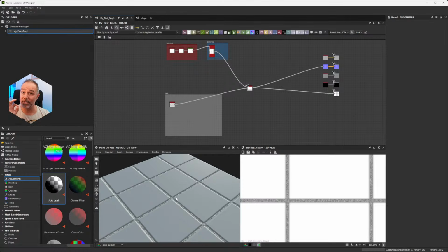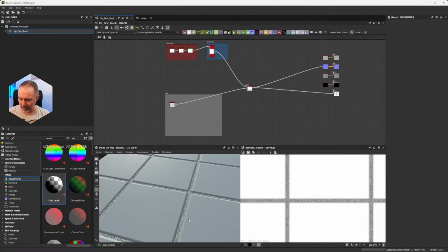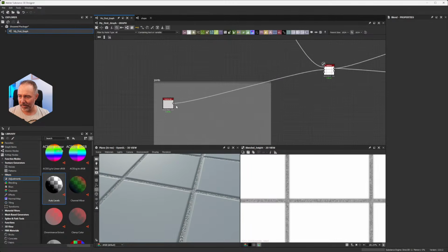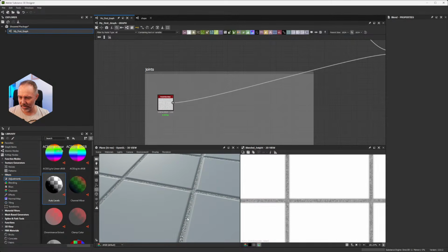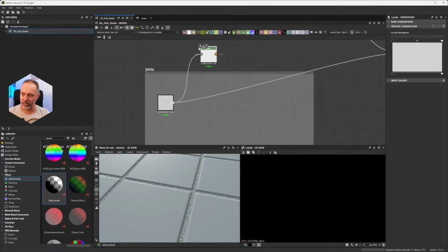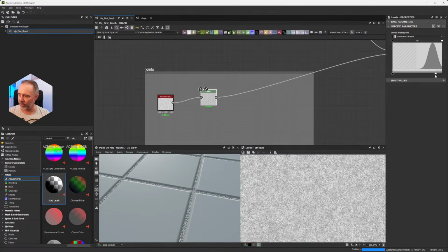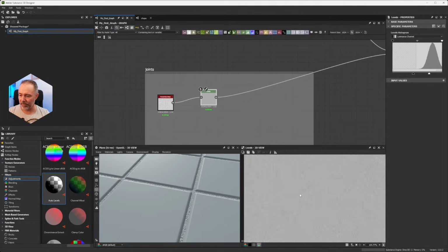Even if the roughness is really important for the believability of your material, first I like to focus on this. So let's continue now. Okay, I'm quite satisfied with this. Maybe here I want to diminish a bit the strength of that. So to do this, if I were in Photoshop, I would use a level node and do something like that. And I would diminish the value here, to diminish the amplitude of the grayscale variations.